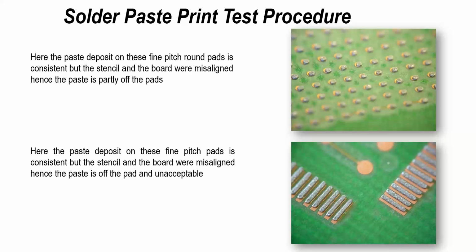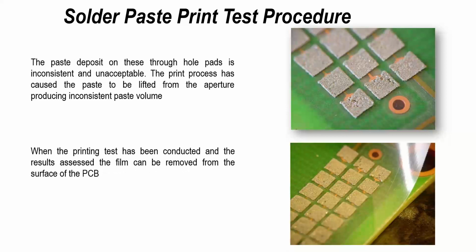Bottom right, again, another QFP, you can see it's misaligned in one direction, which is effectively taking it off the pad in two directions, as you see. But again, this would be unacceptable because the pads on the right-hand side of the QFP are actually touching with the solder paste. So that wouldn't really be acceptable to most standards.